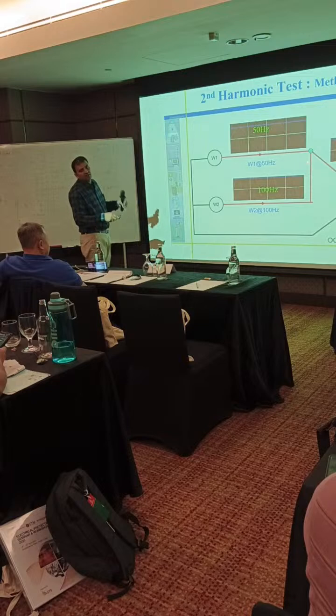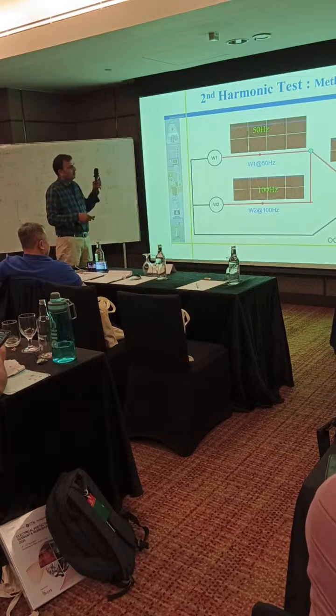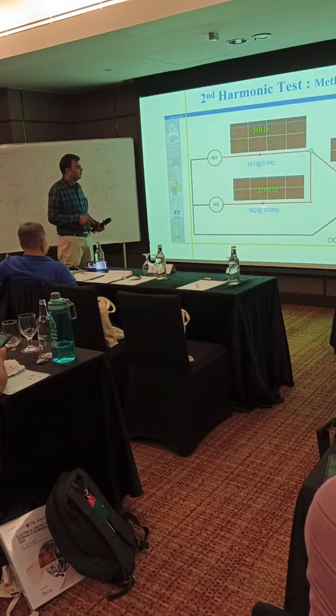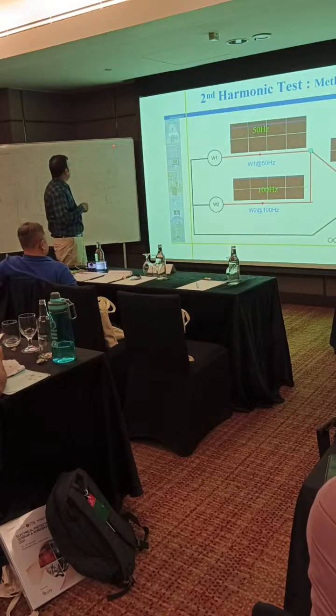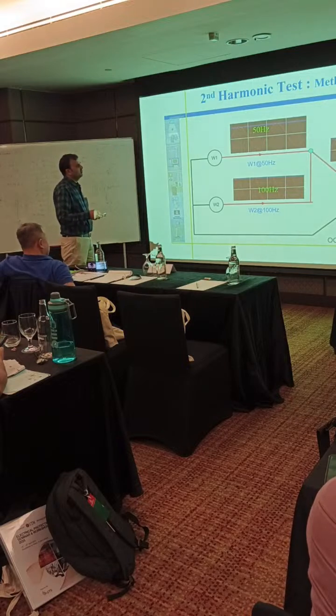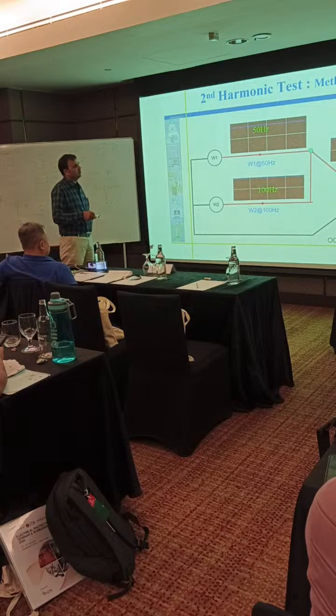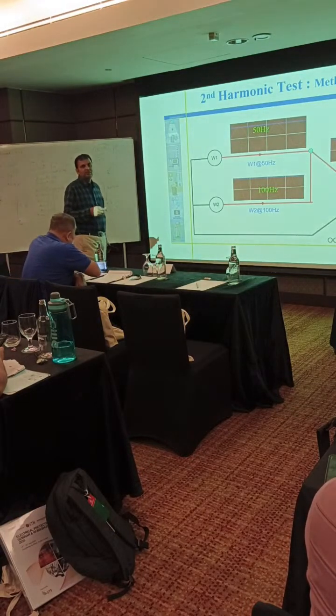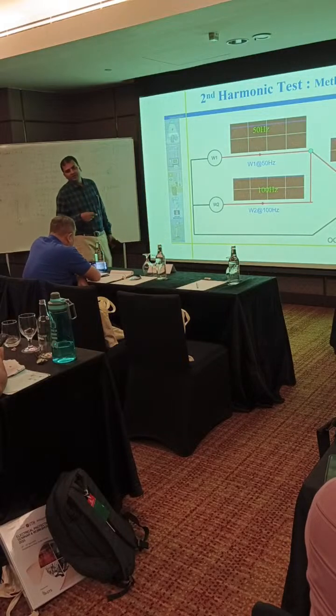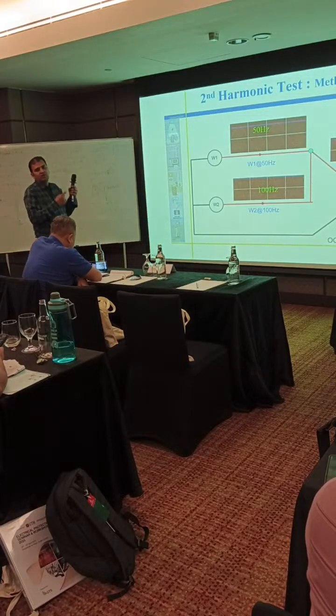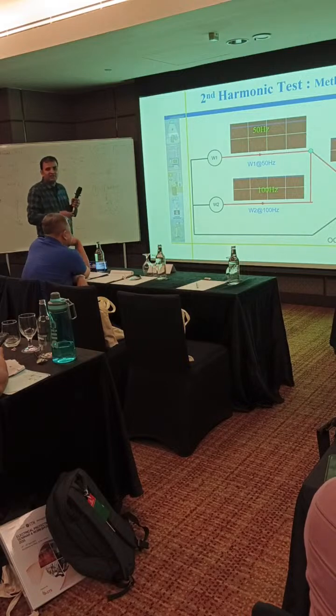It depends on the value of the winding 2 current. If we are injecting equal values, then most probably it will be like this. When we reduce it and get the tripping, at that tripping time the waveform will not be so distorted because it is near the fundamental current. When we have an equal value, then you can easily identify the second harmonic.